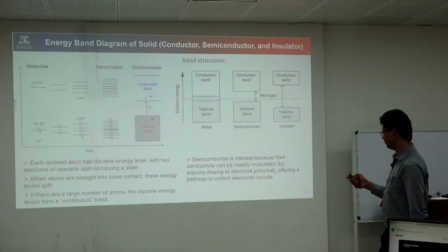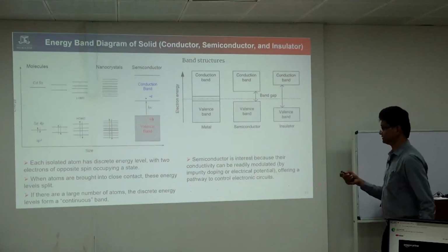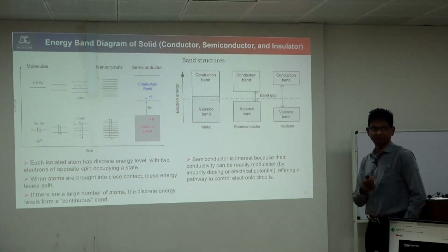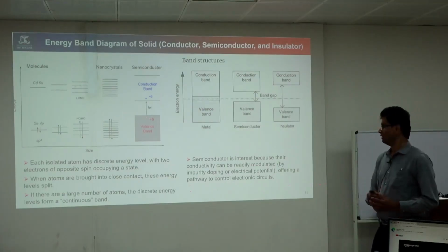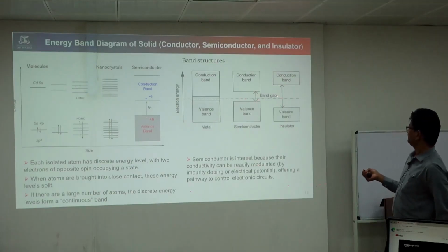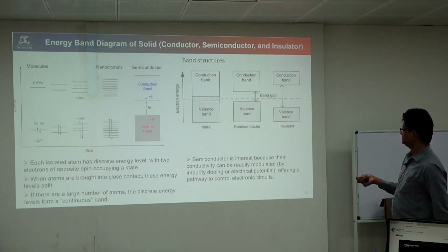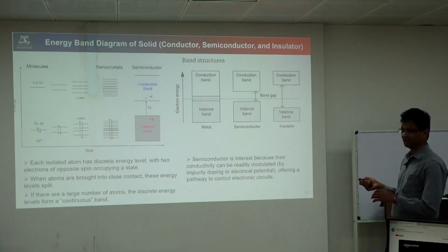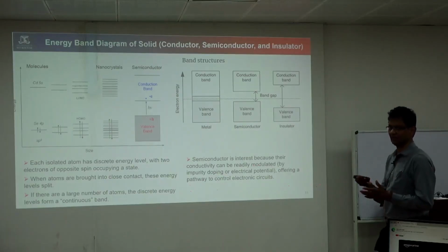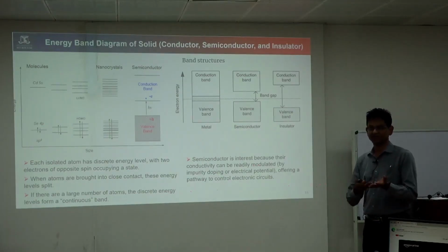And if we talk about the main difference, let's understand a little bit about the energy structure, okay? Everyone knows, I remember, what a band is. So semiconductors work on the band structure. We know that for metal, both the valence band and conduction band overlap so that the electron can easily be conducted, because in metal there are a lot of free electrons. There is no barrier to conduction of the electron.